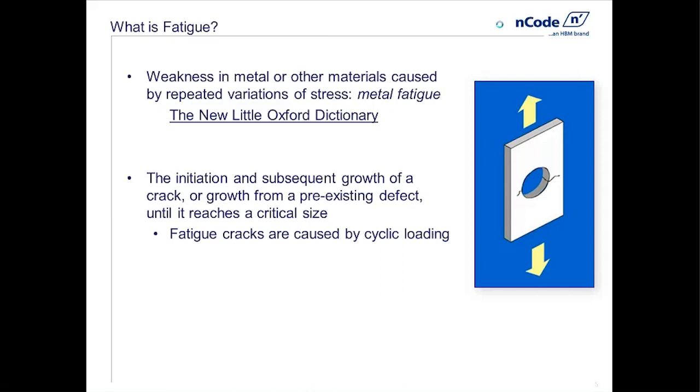In this case of the bridge that I just showed previously, the loading may not change much. In that case, on the bridge, the biggest cycle of stress is actually caused by temperature differential, changes of temperature. So when I say loading, I got to be careful. I actually think it's the change of stress we actually care about. Change of stress could be caused by change of solar loading, could be caused by vibration, could be caused by bumps in the road, and so on.